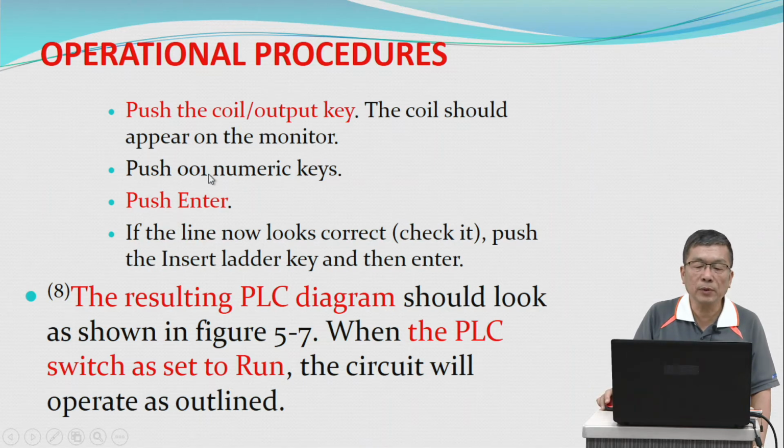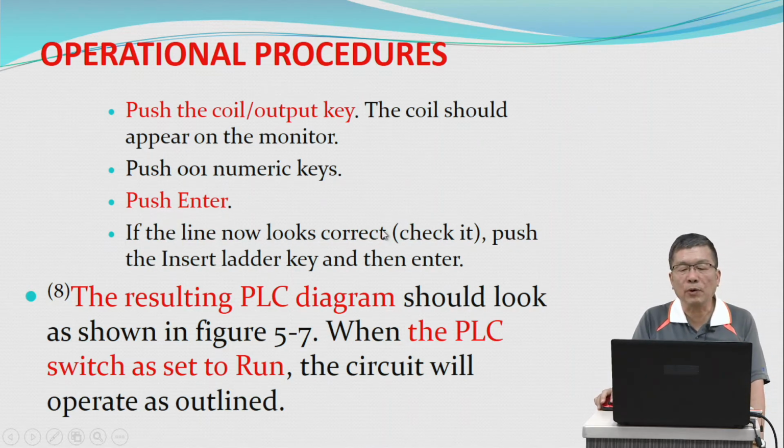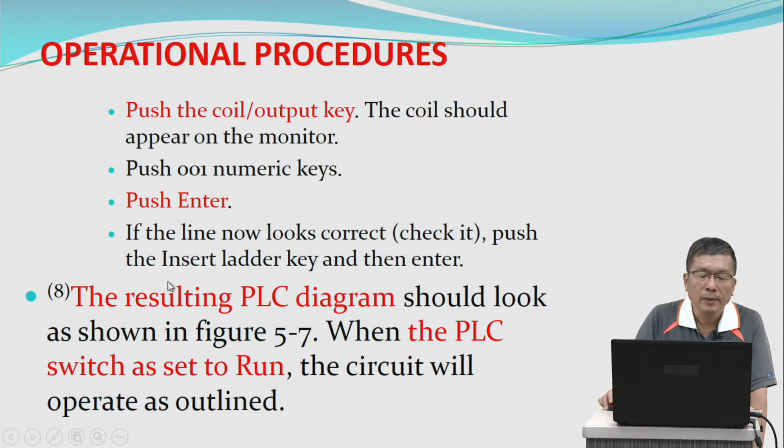Push 001 numeric keys. Push enter. If the line now looks correct, check it. Push the insert ladder key and then enter. The resulting PLC diagram should look as shown in Figure 5.7 when the PLC switch is set to run. The circuit will operate as outlined.